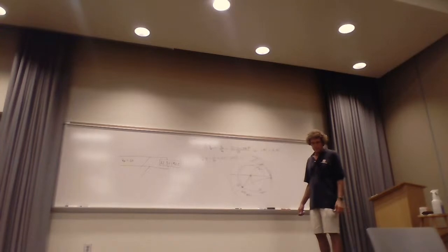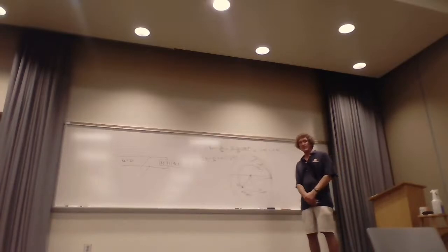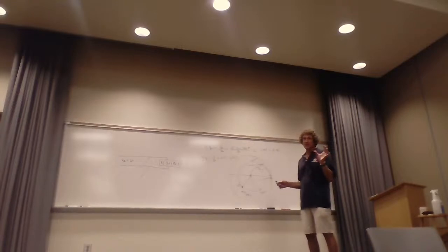Now suppose this antenna network is to be used as a receiver. Use a Smith chart to determine the impedance looking into the matching network. Wait a second. The source with the 50, read that again. Design an open-ended shunt stub matching network to match a half-wave dipole transmitting antenna to a source with 50 ohm impedance. I'm assuming he's talking about a transmission line. There's a couple ways to do this. If it's just 50 ohms, then we want the input impedance to be just 50 ohms, but it'll get there anyway this way.